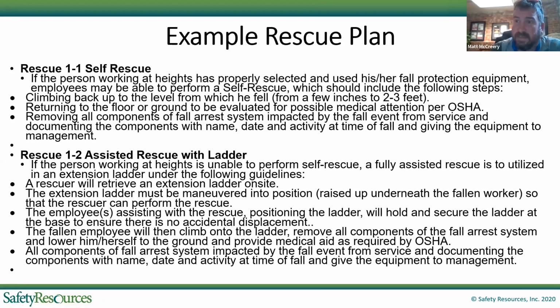Maybe the gutter edge is 14 feet off the ground. We can use a ladder rescue. But I always, always, always recommend, if we're using a ladder rescue, that we bring that individual back up to the work surface so that their fall protection does not have to be disengaged in case they are in shock or otherwise compromised or injured.